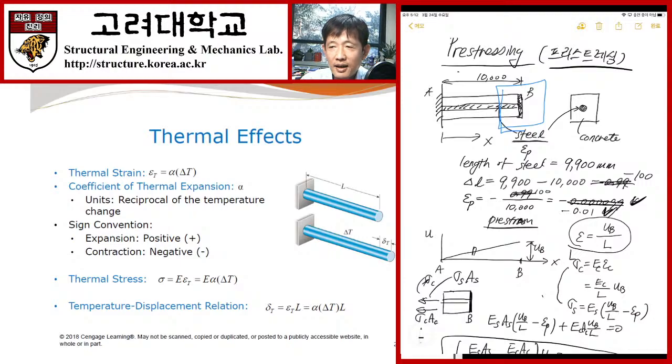Okay, today I talked about and reviewed how we approach statically indeterminate structures. The first approach was the procedure given in the textbook, the so-called displacement compatibility method. The displacement compatibility method is nothing but the principle of superposition for linear systems.